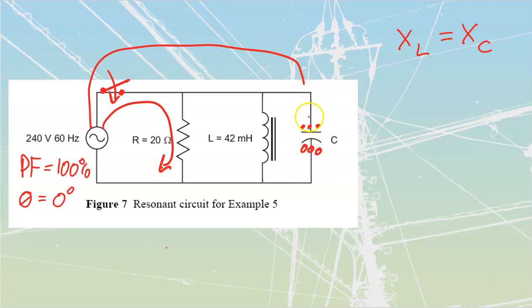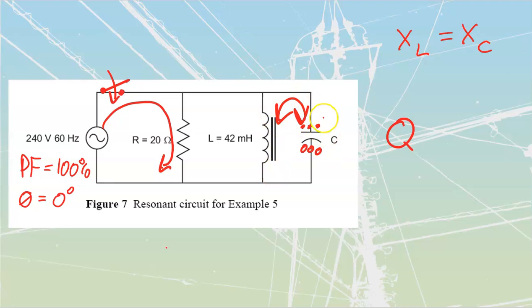But it's only going to continue to build until it fills that plate, until the electrostatic lines of force are giving us all that pressure, and we've got the maximum number of electrons on that plate. Once we fill this thing to its maximum, based upon Q, our coulombs, then this current shuts off. This one continues to go, and at that point, the electrons that we've stored on here start to swish, swish, back and forth from inductor to capacitor.